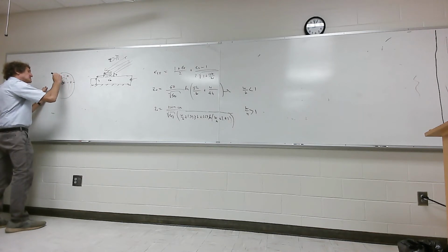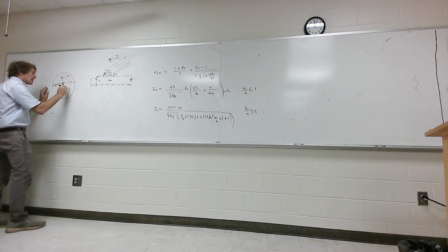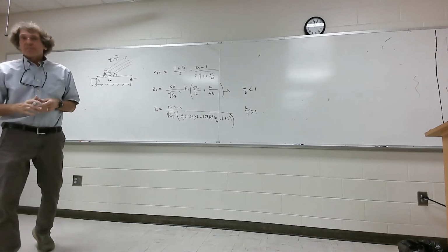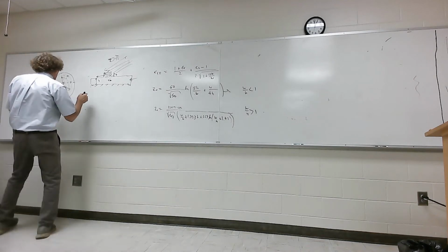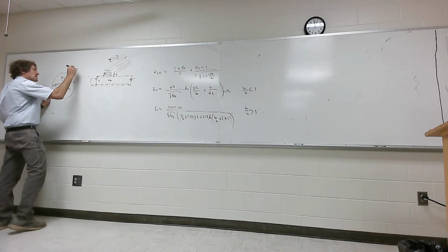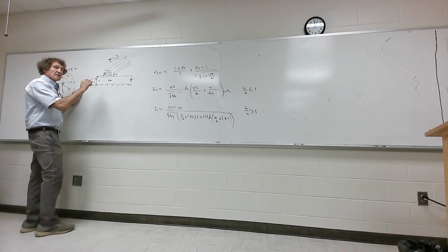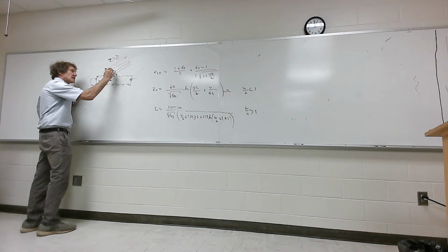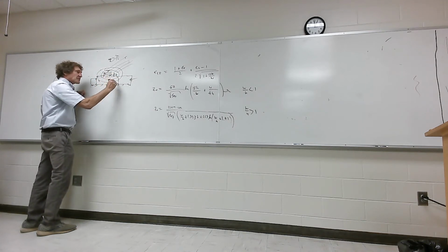These would be the lines that dictate the actual path the charge would take if it was being moved by the electric field. Both the electric and magnetic field are orthogonal to the path of propagating energy. Do y'all follow me? That's called transverse electromagnetic, TEM. It's TEM mode. You will have a TEM mode if this transmission line is operating correctly. You basically have contours like that of a magnetic field, and the electric field would be doing this.